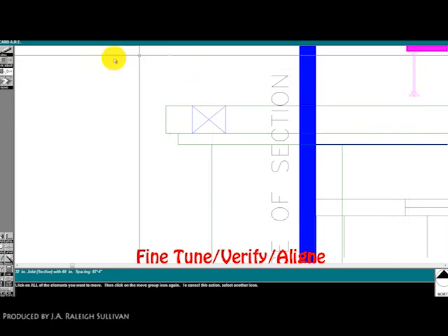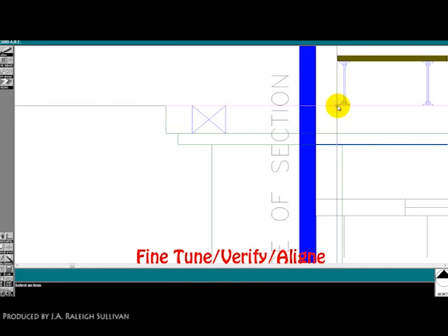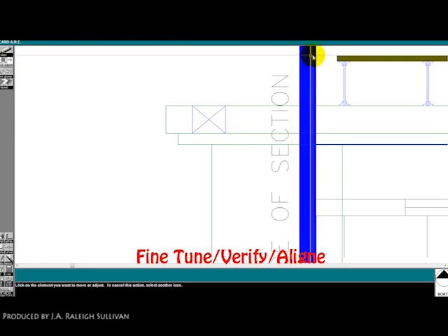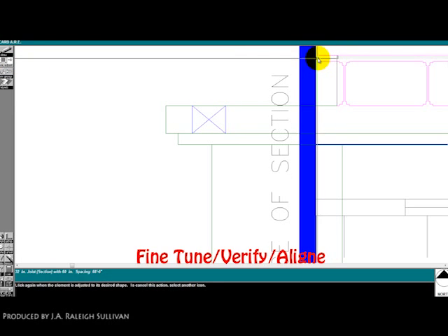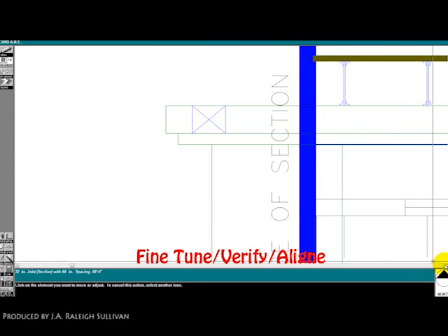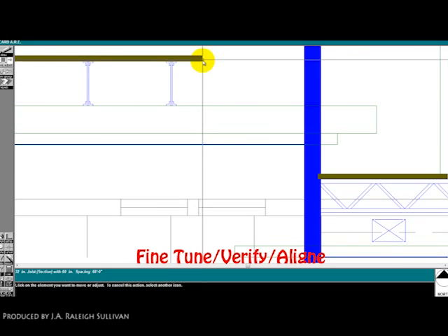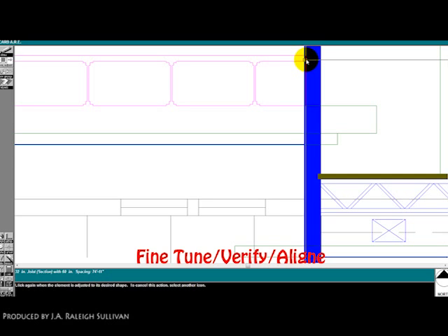Now I'm going to move the joists over. And since we're drawing the joists in section, you have to press the Move Group tool. I'm going to just click that in there so it's a bearing connection. Same thing over here, and just kind of click it in. 2 little clicks in, or 2 inches.